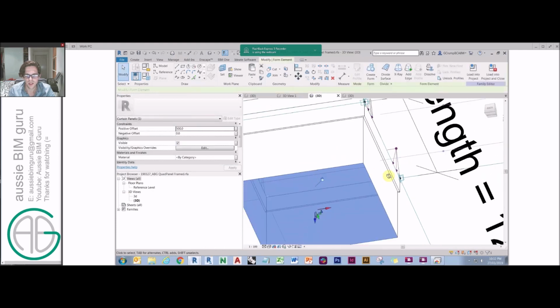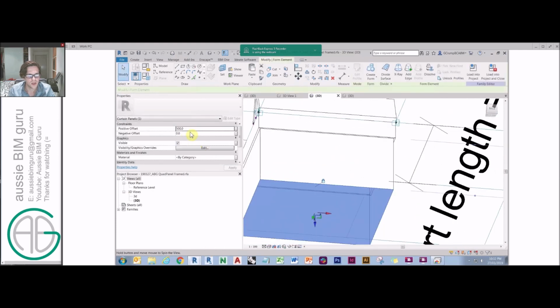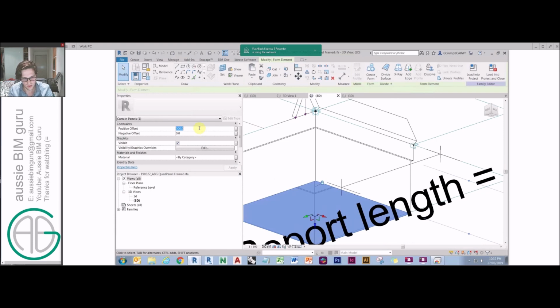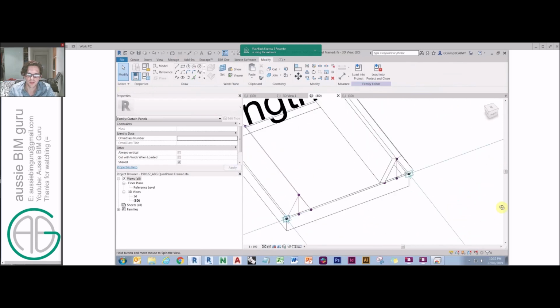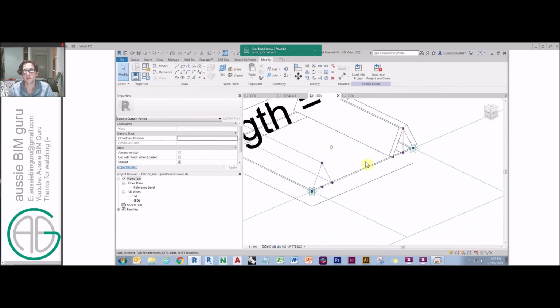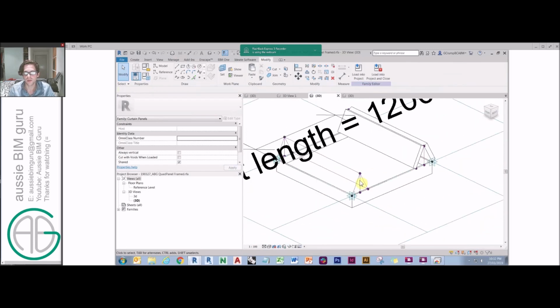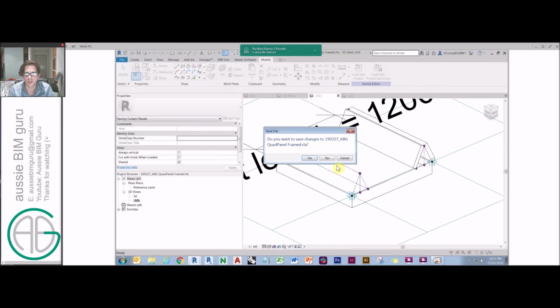In this case, we can actually inset it by setting the positive offset to -50 and the negative offset to 60 to end up with basically a cumulative 10 millimeter thickness in relation to this face. So in principle, we've set up the framework for a panel which will respond to the movement of these points. So I won't move these 4 here because I'm just going to jump to the next iteration of the family.